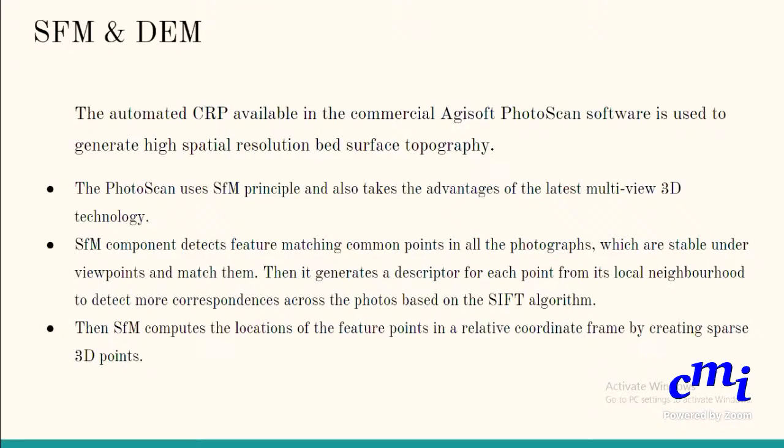Yeah, so a little bit about SFM DEM. Here they used the Agisoft PhotoScan software. PhotoScan uses the SFM principle and also takes advantage of the latest multi-view 3D technology. The SFM component detects common feature matching points in all photographs which are stable under viewpoint changes and matches them.